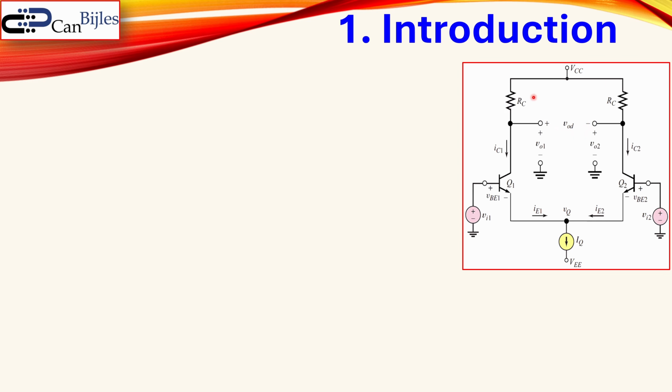We also have here the RC, which is exactly the same at the right side for our differential amplifier. So this circuit is actually a symmetric circuit. In order to bias the circuit for the currents, we also have here a tail current, which is the IQ. Now let's go one by one and discuss this circuit in more detail. Mostly we would like to have a matched circuit. That means Q1 and Q2 need to be identical in order to suppress the signals we don't want.